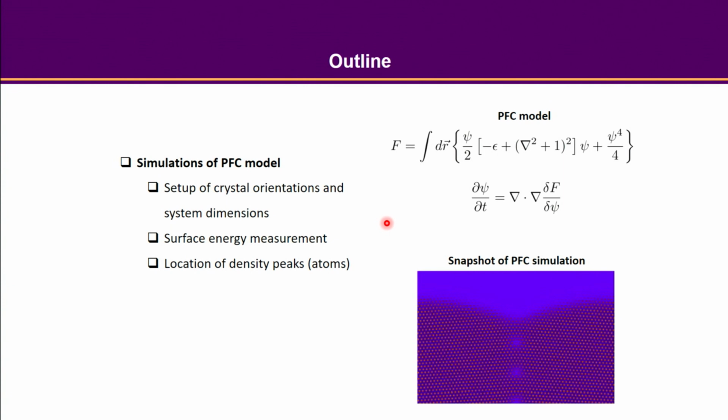But in the phase field crystal, it's kind of tricky because like the calculation you have been doing for the phase diagram, you have seen that the free energy density for the solid liquid, they are not exactly the same, right? We have seen this common tangent construction. So how to exactly calculate the surface energy or excess energy for this solid liquid interface or the grain boundary solid-solid interface, that will be something I'm going to talk about today, all right?